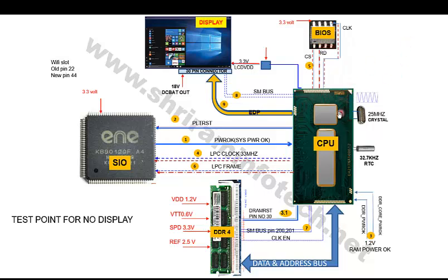In that case, you have to match the CSME, and only then will the display appear. This applies from 9th generation onward laptops. For older laptops, you don't need to worry about that. You can straight away flash the BIOS and the display will appear.